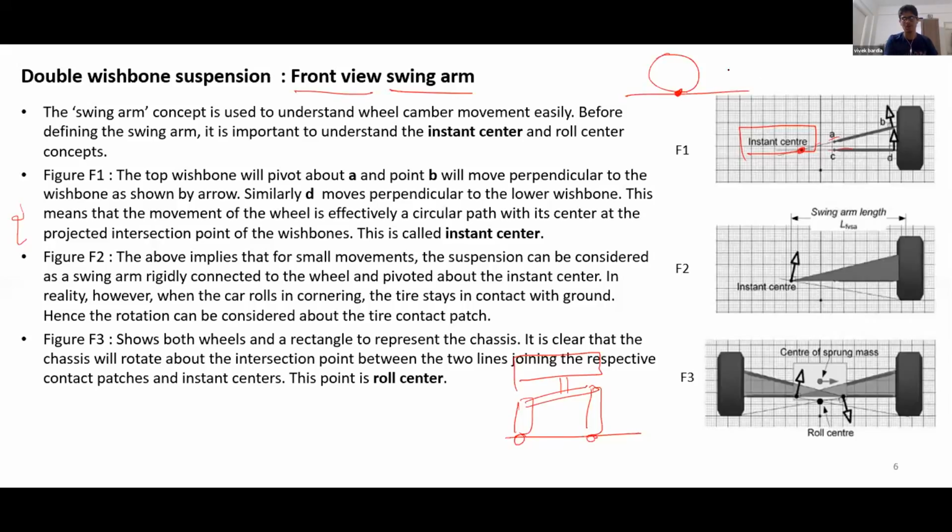The same motion can also be considered as rolling about the center of mass as well as a translational motion of the center of mass. But at this point, the entire vehicle is in pure rotation. That is the instant center. Similarly, for a four-link mechanism, the instant center is the point about which all three links are in pure rotation, right?